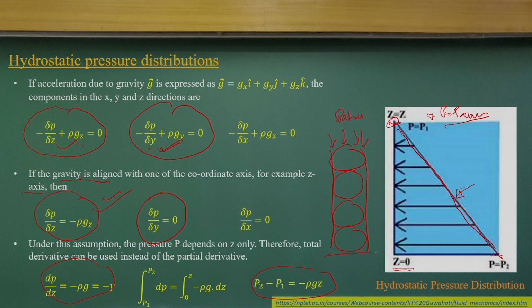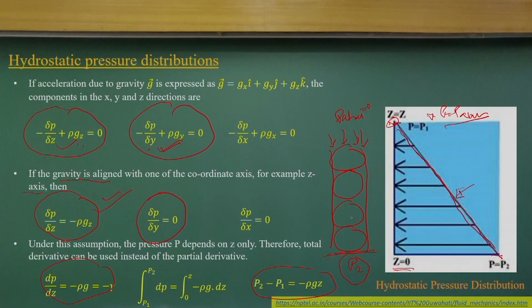Okay. I want to know what the pressure will be at this point, let it be P2, nothing else. This pressure will be because of the atmospheric pressure; if I make that 0, then what will this be? It is the weight of the liquid, that is what will be the pressure on this: weight of the liquid divided by the surface area. If I consider the unit surface area, that means the unit weight of the water multiplied by Z, that is what will give the pressure here.